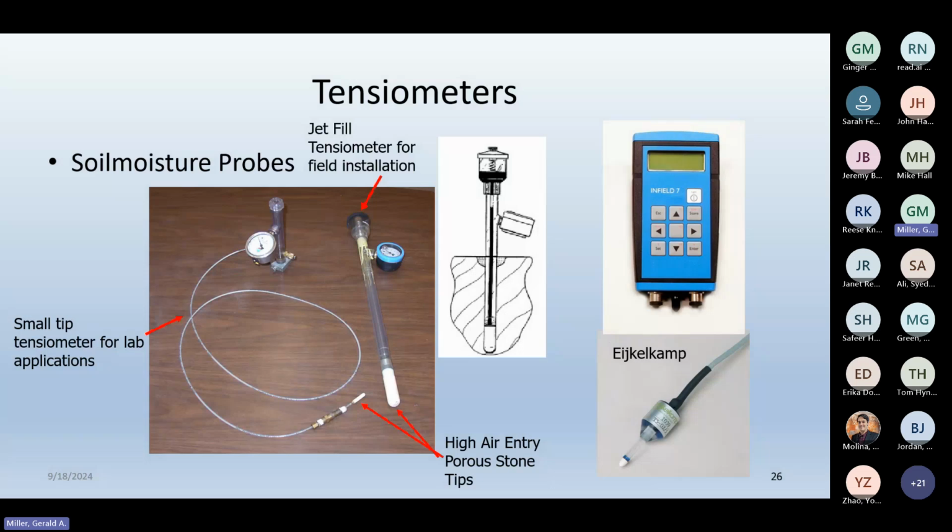It's basically cavitation. Water at room temperature cavitates at about minus 100 kPa gauge. And what that means is the water molecules are sheared apart and you get gaps in the system, air in the system essentially.